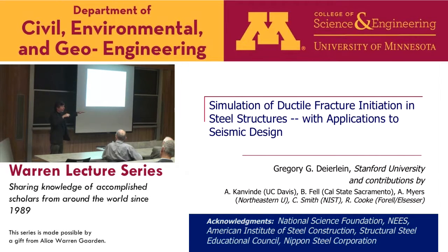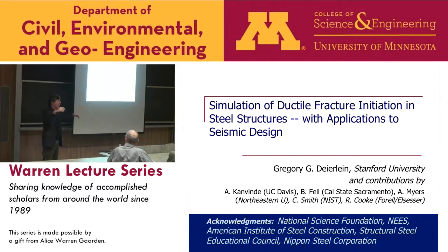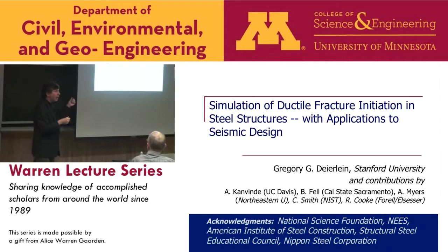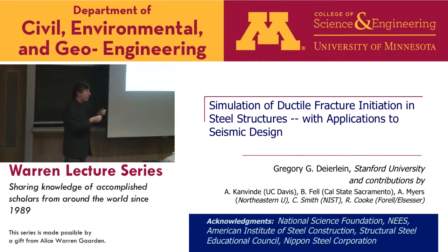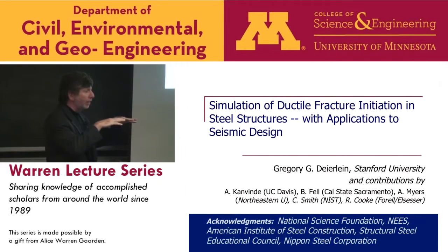Frankly, I think our design provisions have been tested on small things in the lab, and then we use them for massive structures, where, Paul, you used to design things with 4-inch thick plates with bolted connections. So I think these models are ideally suited to that because those are cases where you tend to have ductile fractures. You'd have to build a finite element model that represents the geometry with the bolts and even get the friction, clamping and so forth right. But if you could build the finite element model and calculate the stresses and strains, this void growth model would give you a way to reason when you would start to see ductile fracture initiate. Thank you. Okay. Other questions?